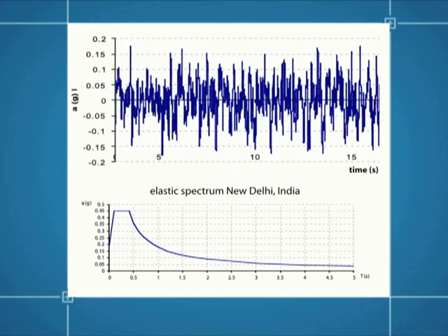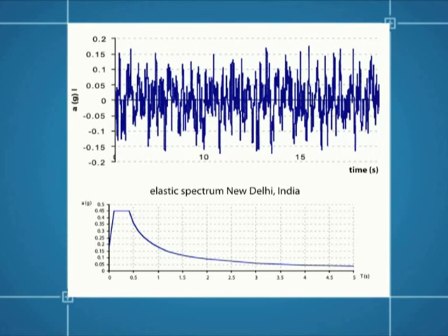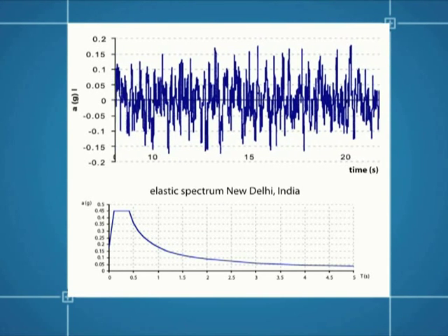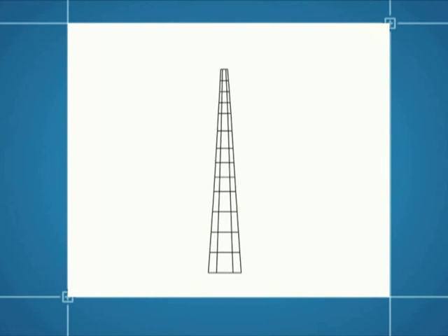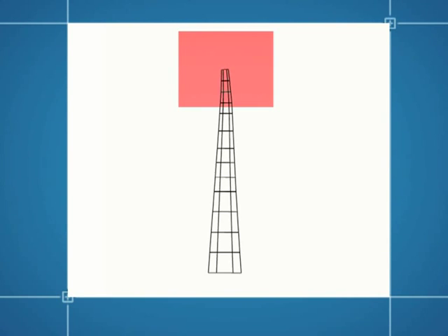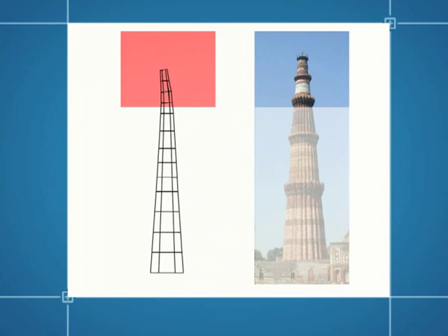Several accelerograms, compatible with the response spectrum defined in the Indian Seismic Code, were applied to different models of the Qutub Minar. The dynamic analysis proved to be more representative with respect to the seismic behaviour of the Qutub Minar, since it can detect a number of peculiar vibrational characteristics of the tower that cannot be appreciated by applying a conventional pushover analysis. The earthquake load simulations indicated that the structure generally manifests moderate displacements up to the third balcony, and a localized large amplification, in terms of accelerations and displacements, is detected in the upper part of the tower.